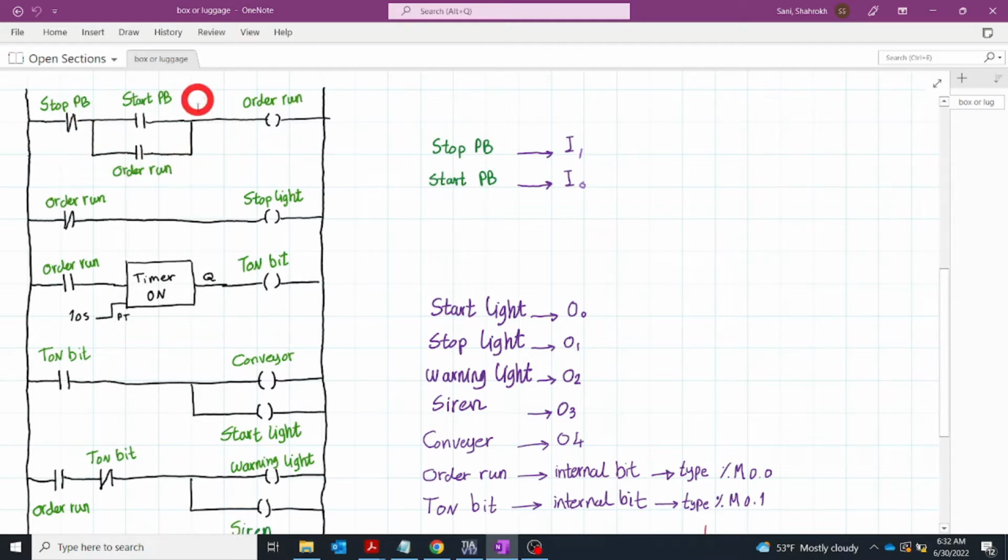How does it work? With this ladder logic, you have these three inputs and one output. The stop button is normally closed, so if you don't push it, you have power at this point. The start button is normally open, so if you don't push it, the power is stuck here. If you push the start button, you pass the power through to your output, and your output has power, or you fire your output.